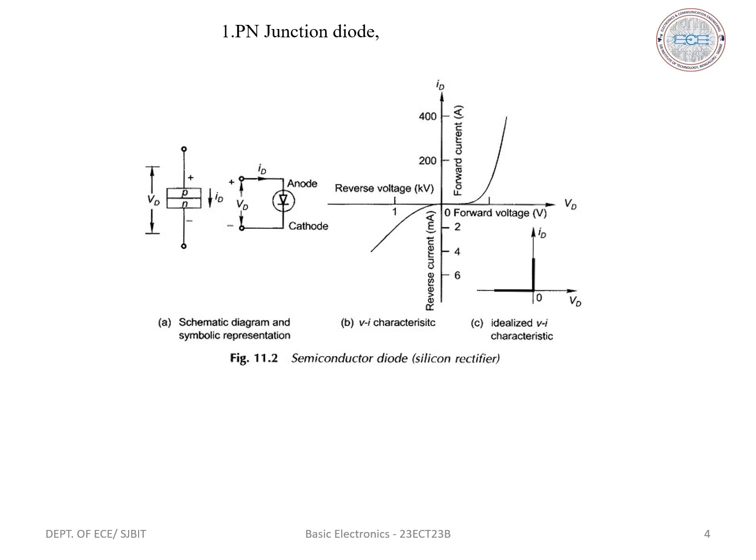The forward current is a conventional current that flows from anode to cathode. Therefore, it is considered to be a positive current and the forward characteristics appear in the first quadrant as shown in the figure. The voltage at which the forward diode current starts increasing rapidly is known as the cut-in voltage of a diode. The cut-in voltage is very close to the barrier potential and it is denoted by V alpha. Next, we have reverse bias of a diode.